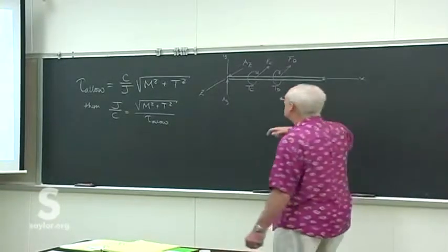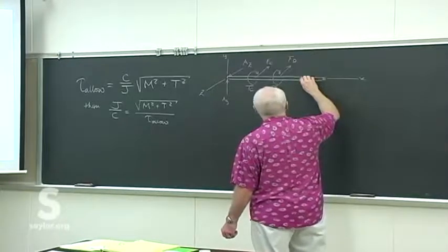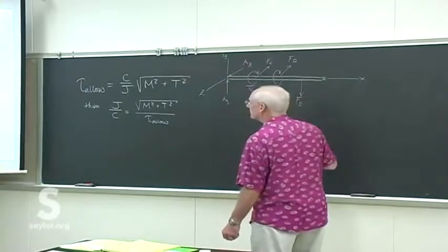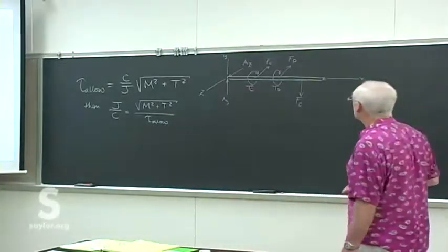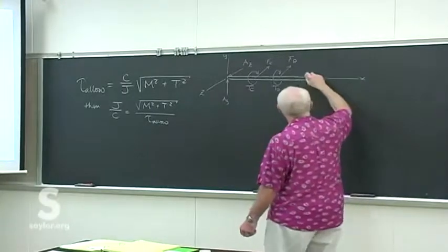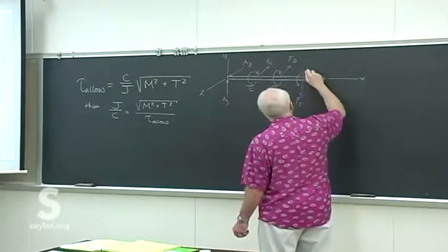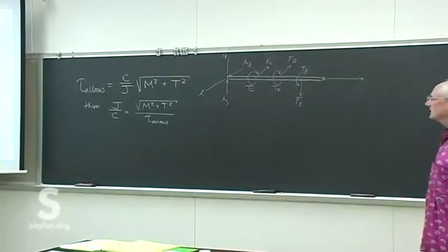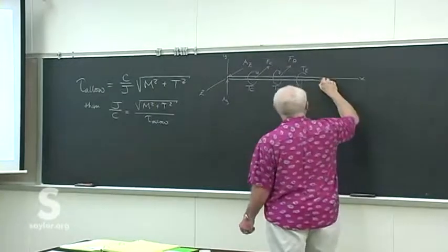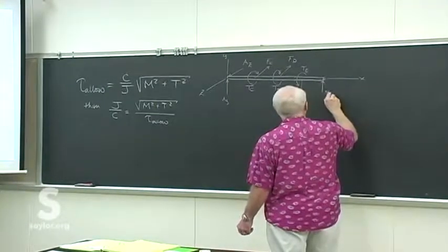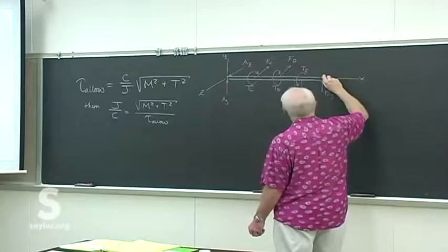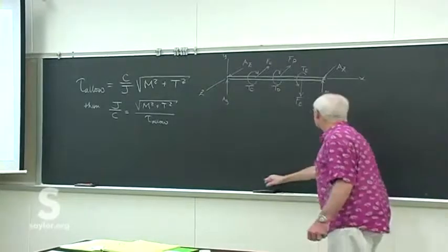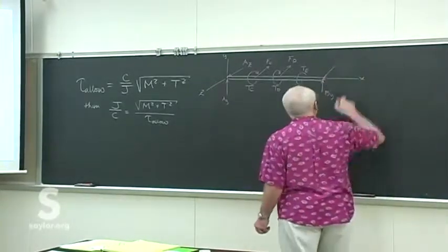And then at gear E, due to the placement of where the motor happens to be, we'll have a force in that direction. That's Fe. I'll show you how we get that in a second with some more of the details of the problem. And then it's got an applied torsion in the other direction. And then we have the two reactions at B, again assuming no axial load.